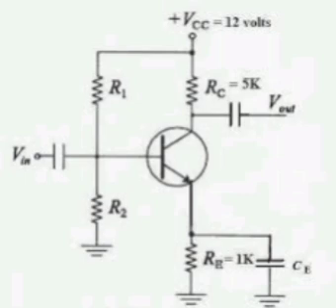An electrical load absorbs an average power of 85 kilowatts at lagging power factor of 0.85. If the load operates at 240 volts RMS, calculate the complex power and impedance of the load.